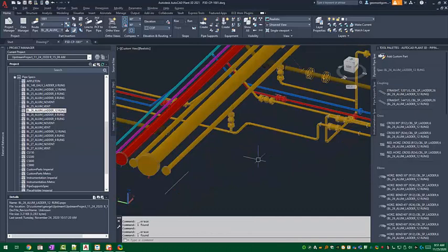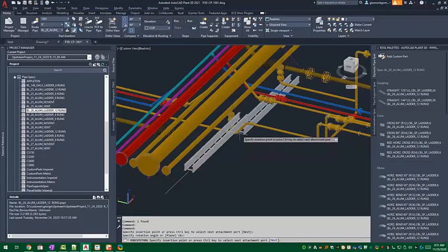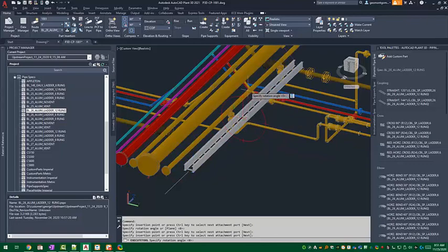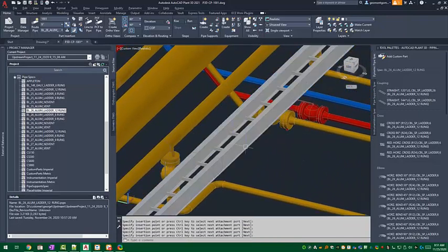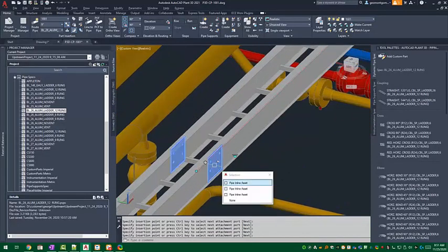Here I'll show you again. Notice that when I place the component, I can also select the endpoint of my last tray to snap and place another piece sequentially afterwards. Fastener components that make tray sections electrically continuous are attached automatically and do not require the user to place them. We built ELECTROWorx to specify the correct fastener depending on which two pieces you're trying to connect.